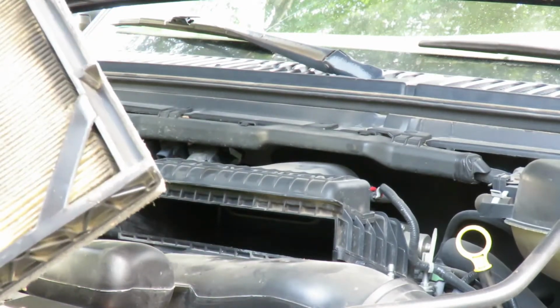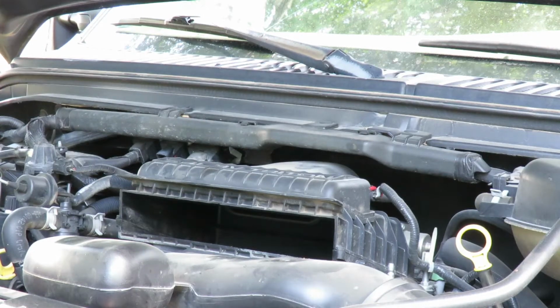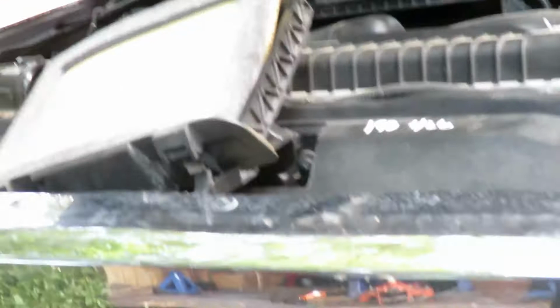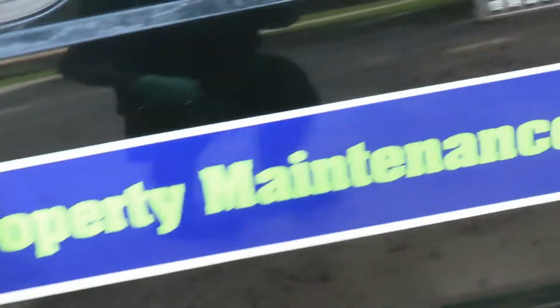So you definitely want to, that air filter is kind of dirty. So what we're going to do here, I'm going to leave the air filter alone, and start the vehicle up again, and we're going to see if it picks up power, because a clogged air filter, just that simple, will cause the vehicle to lose power. I'm not saying that this is the problem, but always start with something simple, and then work your way up. All right. So let's get in here.